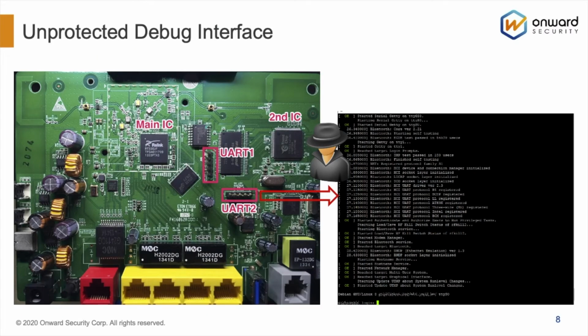And for IoT device hacking, we can touch the device. We can physically touch the device. So I can disassemble your product, open the case, and try to find some special debug interface. For example, IoT devices sometimes have a UART interface or JTAG or I2C. For the security researcher, we will try to identify what kind of debug interface is used by this device. Sometimes I can get information or get a system shell through the UART, JTAG, or I2C.